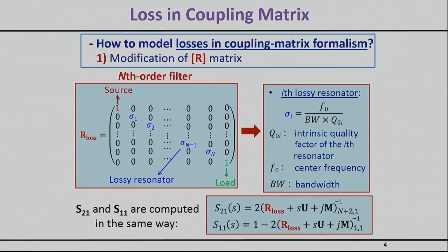Now, the second step, once you know the filter order, is essentially how are you going to estimate this more accurately from the coupling matrix synthesis technique. Again, the equation I just gave you is more of a first order approximation, and later on I'll give you examples that teach you how accurate that thing is. But there is a slightly more involved, just again algebraic calculations, nothing too difficult, where you can make the estimate even better. So we're going to be using these sigma factors that you see right here.